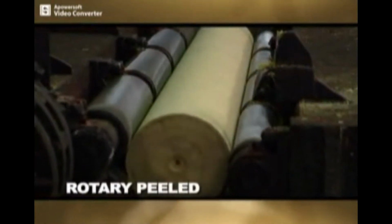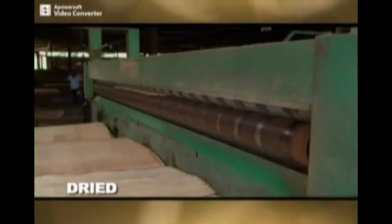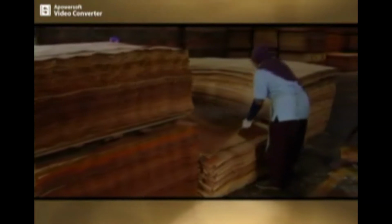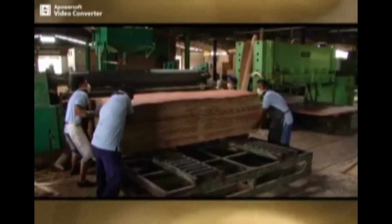The cylindrical block is then peeled into veneers and clipped to the required width. The wet OPT veneers are then dried at the veneer dryer. The next process is lamination of veneers into panels. Firstly, the dried veneers are applied with thermosetting adhesive in a cross-ply layup.